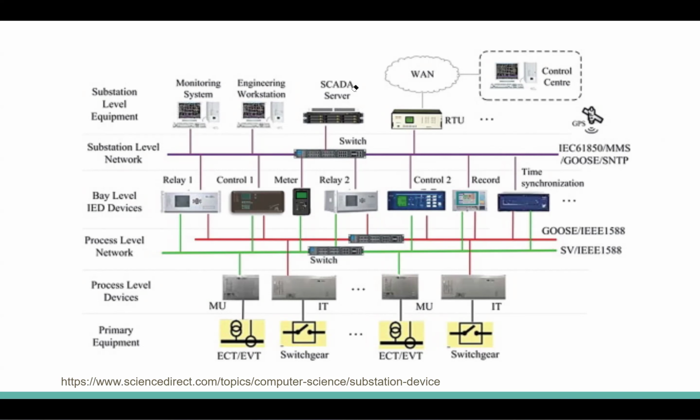You also see this term here, SCADA server. We could also just call this a SCADA IED. We could replace these with IEDs if we felt like it. And then we have a network switch. You see the switch is what everything is plugged into, and it allows everything to talk to each other. This stuff down here is something I'm going to be talking about next week, on Tuesday, where we're replacing hardwired signals with digital communications with SCADA.